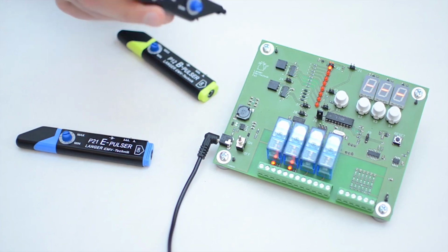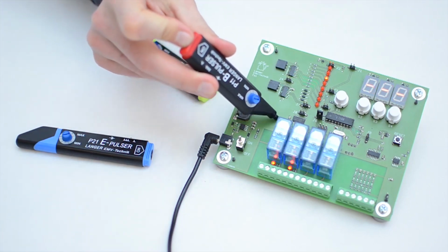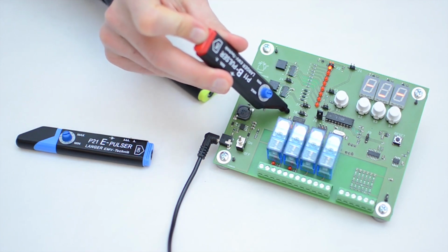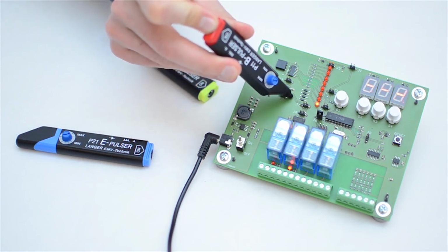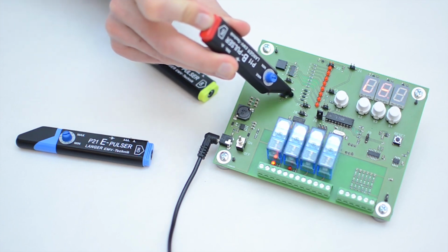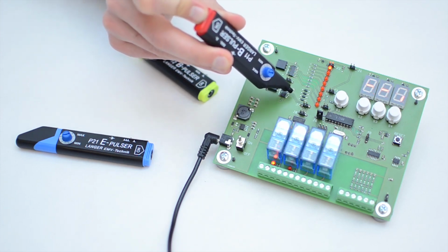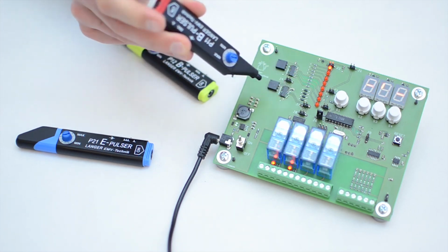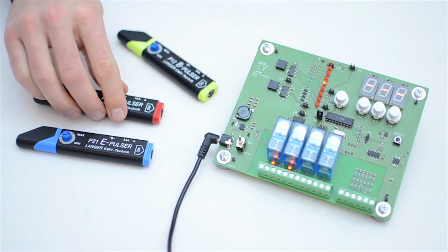Initially, the electronics functions in its normal way. If we move the mini-burst generator across the module and allow a disturbance field to act on this, we can localize immunity weak spots with great precision. In this case, we have used a magnetic field to interfere with the module.